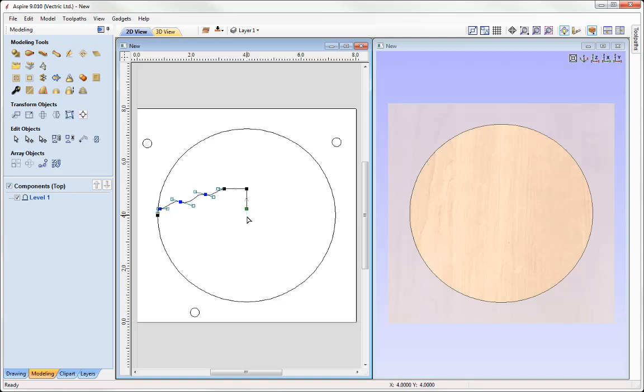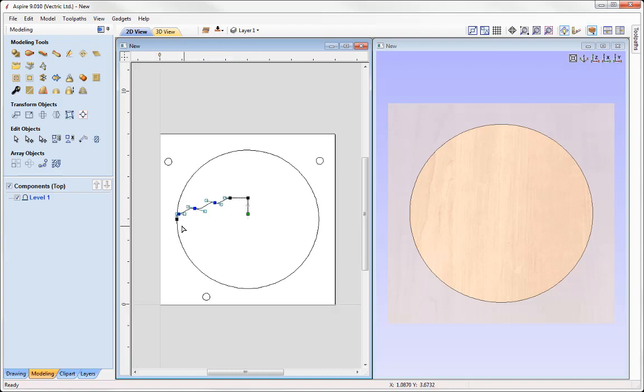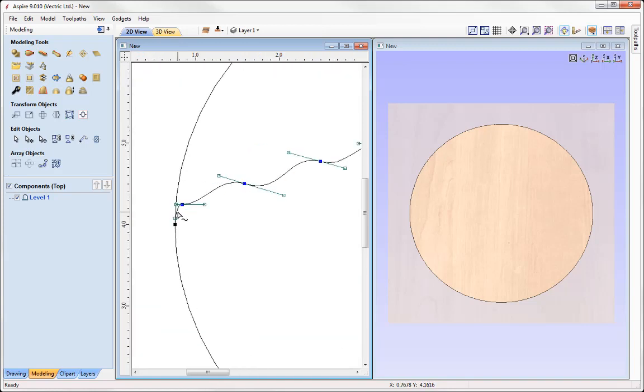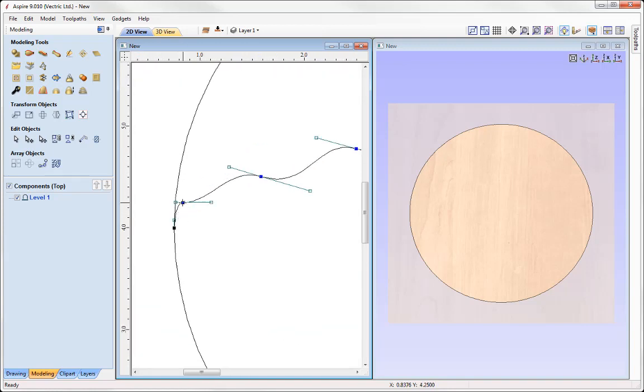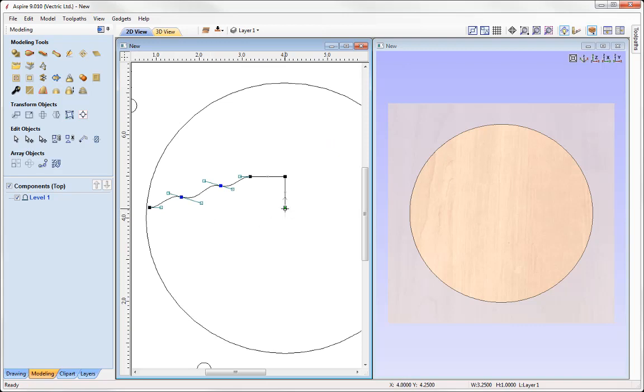Okay, so we took 1/4 inch off that leg there. You'll remember when we originally created this vector, I did it so that this point was at 1/4 inch high. And so all I need to do here is just look at deleting this span here, and we should be able to see that the two line up, and we can see that there. So just bring that back to its original point, so we know that we've lost 1/4 inch on each side of that cross section.